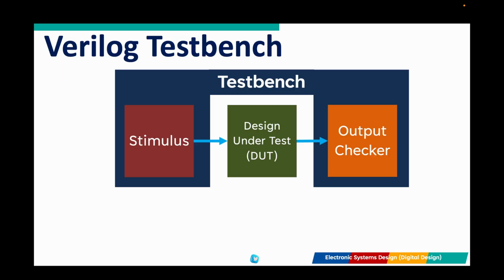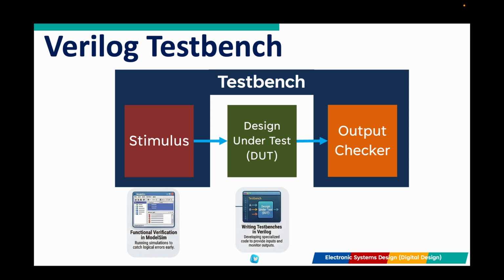Let's dive in. Think of a test bench as a virtual lab environment. It is a special Verilog module designed to do three things: generate virtual input signals, the stimulus, feed them into your hardware design, the device under test, typically labeled as DUT, and observe the results, the output checker. Unlike standard hardware modules, test benches have no physical input or output ports. Everything happens internally within the simulation.